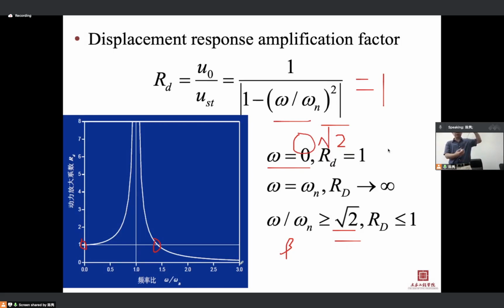I think you already have the homework to derive the equation of motion for this pendulum. And then you can move. This is a so-called free vibration, where we have an initial displacement. Or you can move the support, like with my left hand. The movement of the support is also a dynamic load. We already know this, right? So if you move very slowly, which means the external load is varying very slowly, the dynamic loading is almost the same as the static load.